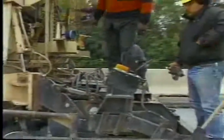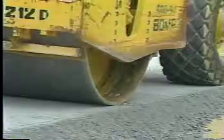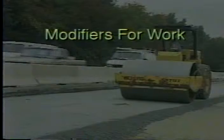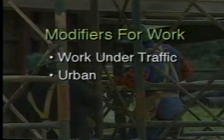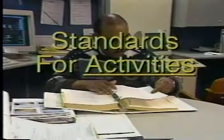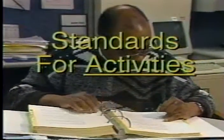Modifiers to the planning standards may be desirable for some agencies to provide more accurate estimates. Only 3 construction conditions have significant effect on manpower needs in most agencies: working under traffic, construction in urban areas, and mountainous terrain. Developing standards for activities involves adapting base planning values and modifiers.